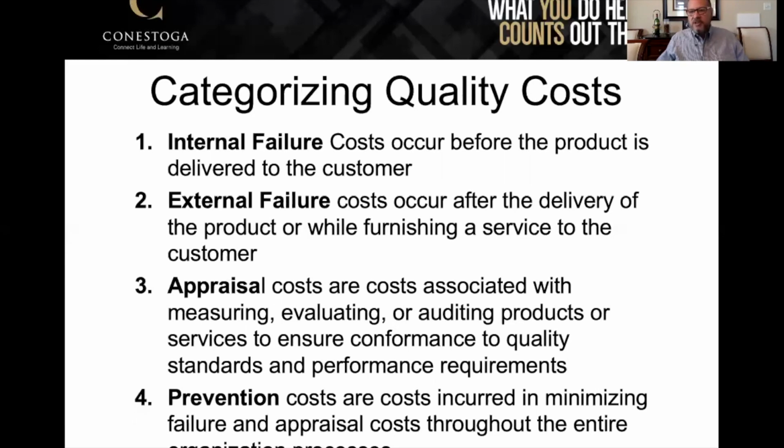One of the ways to prevent that is to have your incoming inspection of the components before they get put onto the board. Now, that won't eliminate every potential issue. If the solder doesn't flow properly in the reflow oven, you could still have an issue. If for whatever reason it wasn't laid out properly, you could still have an issue. And there are some early life failure issues that will come up later on. But as much as possible, your incoming inspection would prevent the issues over here. That reduces your costs very much so.